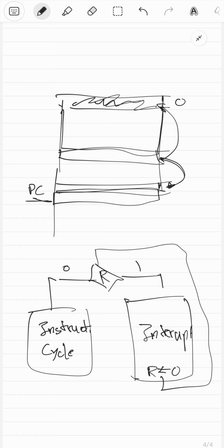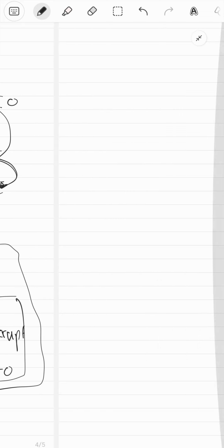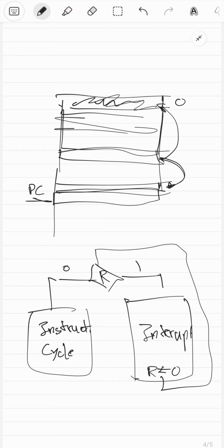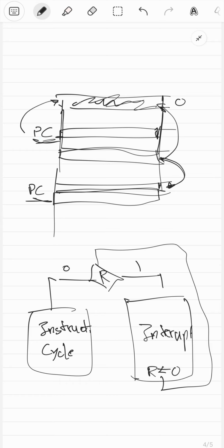That doesn't make sense. Yeah, but another reason this should not happen is, say you are running these instructions, the ones for the interrupt, and then suddenly the user interrupts again. Then at that point, whatever is the address of this thing, the program counter is here, whatever this address is, that's what will be sent to this location, and so the previous data is trashed or overwritten.